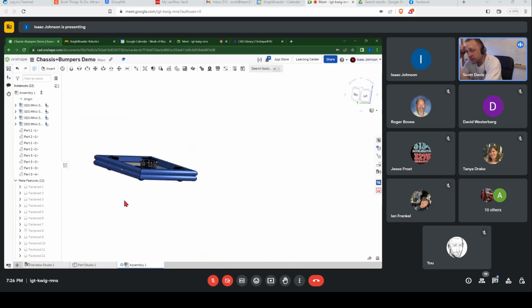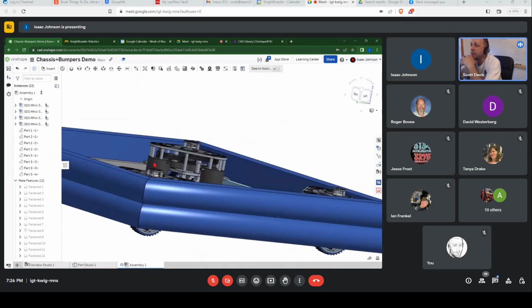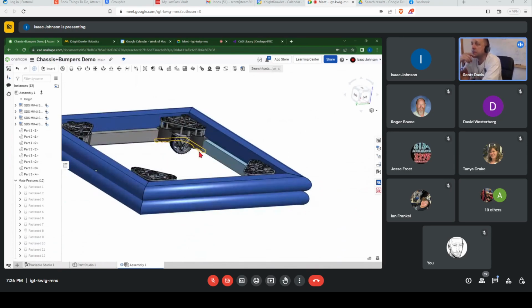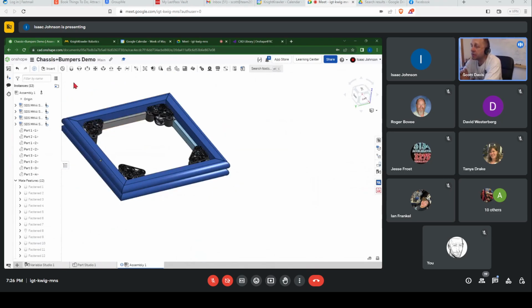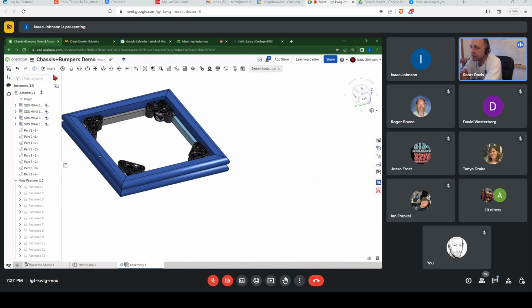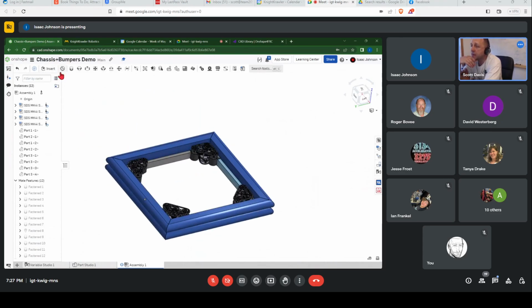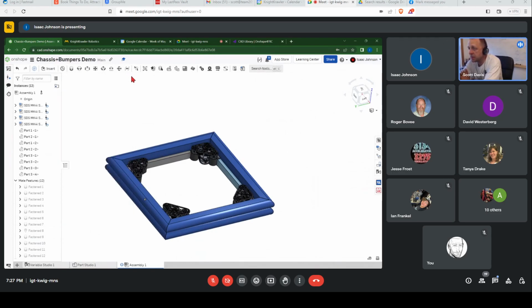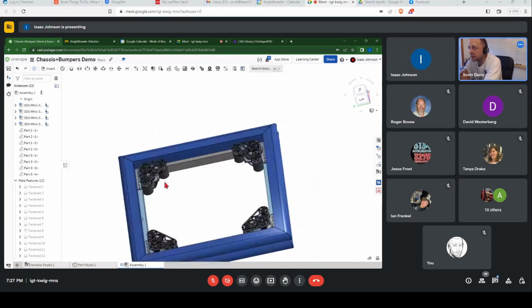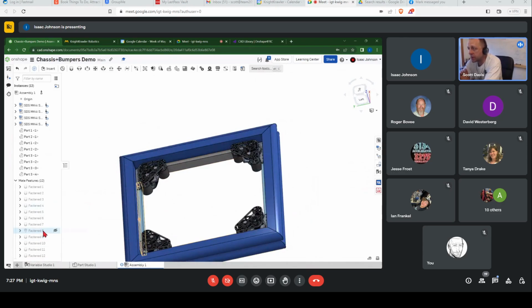Yeah, and one thing about that: when you were putting on your MK modules, you were doing the rotate, rotate, rotate. But one thing OnShape doesn't do is, when he was rotating the entire swerve module, it was only rotating that one plate. If you hit that solve button, it'll move all the other parts that are attached to it around as well, so you can see what it'll look like before you complete your mate. So that's what the solve button is for: when you do the rotation, it may only rotate part of the thing you're trying to rotate, and if you hit solve, it'll redraw everything to line up with the one part it rotated.